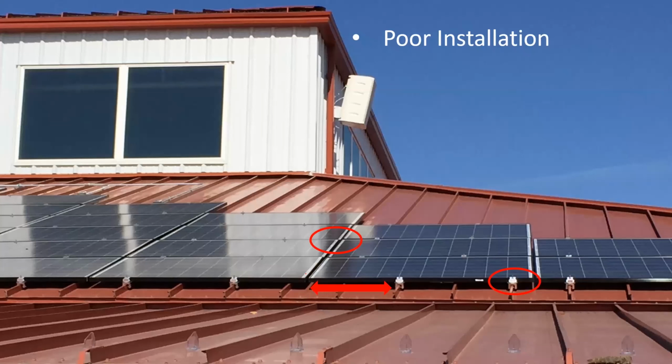This is just an example of a poor installation where you can look at these kind of stair step solar modules. There are different gaps, different places. It's kind of ugly, but also look at these little mounting brackets that are here. This is a huge gap on the end of that solar. You might not know it, but that doesn't even meet the installation guidelines for the solar panel.